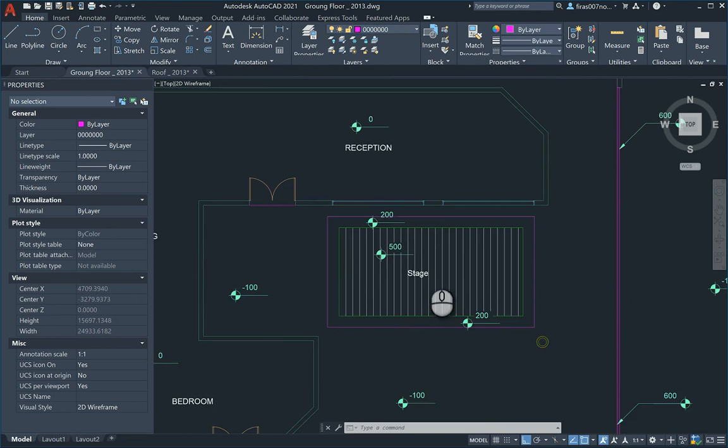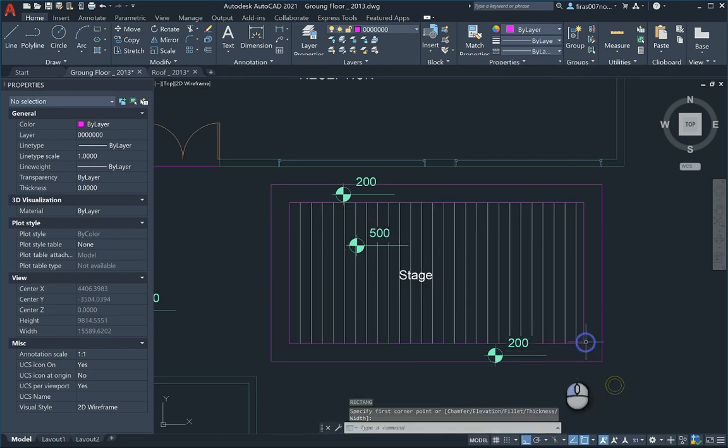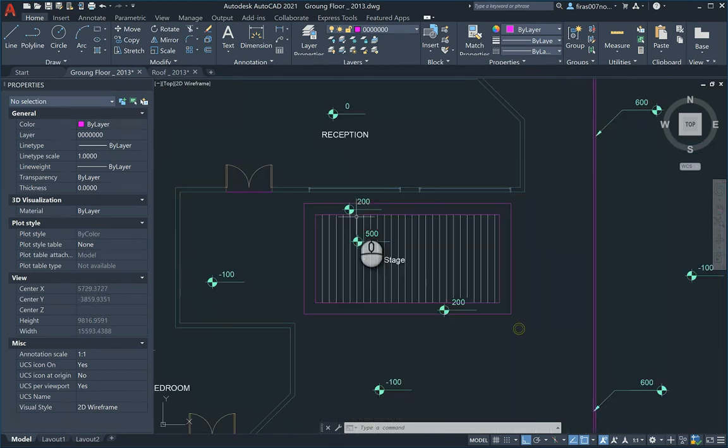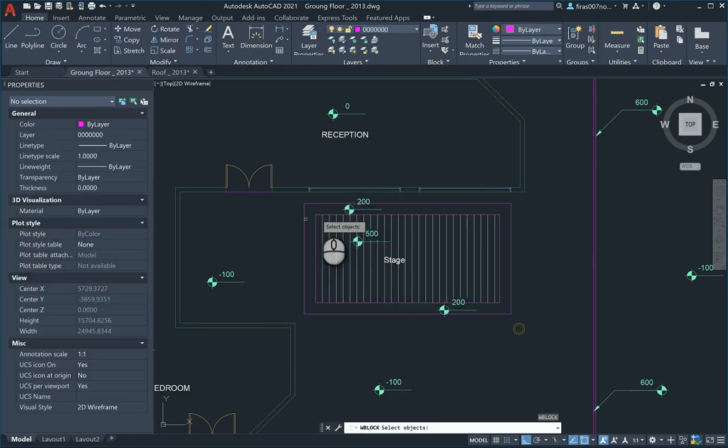It should be located at 500, that's the Z value of it, and its end to be set at 200, so again minus 300, the extrusion. So you know what to do.